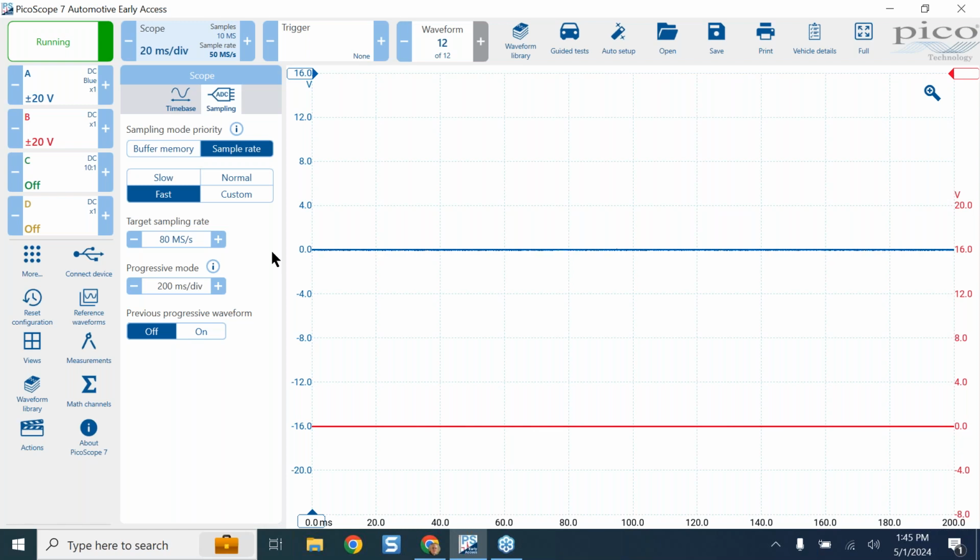The more samples you put on the graticule, on the screen, the number of buffer waveforms is going to drop dramatically, obviously, because you're putting a lot of information on one screen. You put a lot less, you're going to have a lot more waveforms in the buffer. So I just think of it as a teeter-totter event, and I will certainly spend a little more time on that.